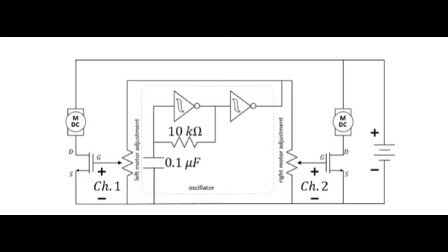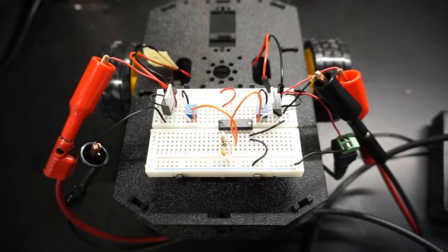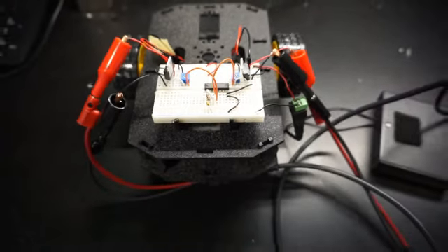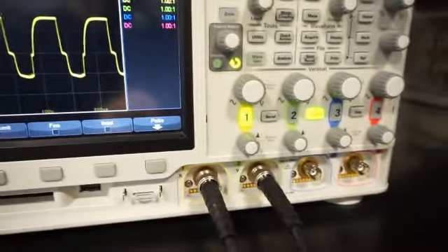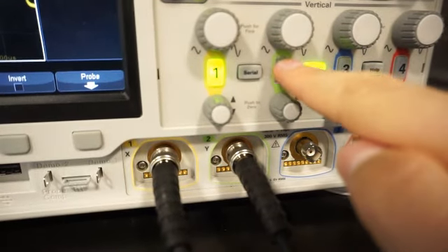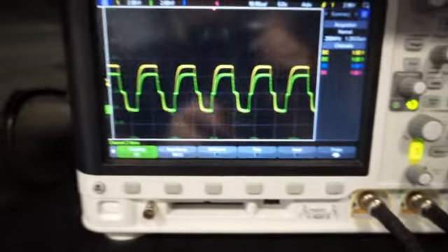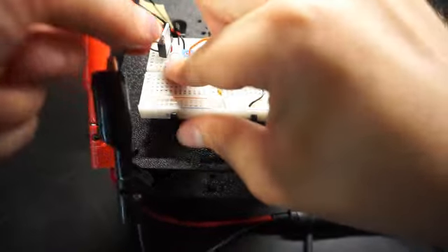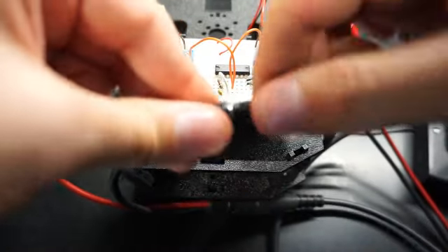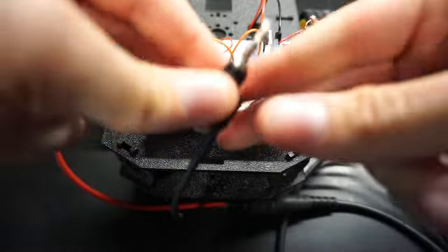Again, the oscilloscope provides a window into the operation of your circuit. Since each black wire of your oscilloscope probes are internally connected within the scope, you must be careful that multiple scope channels connect the black wires to the same node on your circuit. Now we can observe the voltage at the gate of each MOSFET, the voltage that drives each wheel. In fact, the signal is unchanged if the two black banana plugs are combined and only a single alligator clip connects them to your circuit.